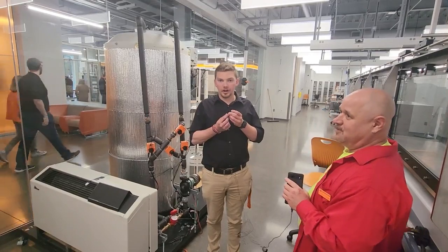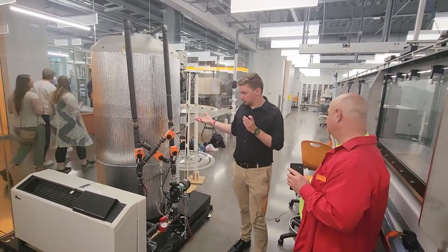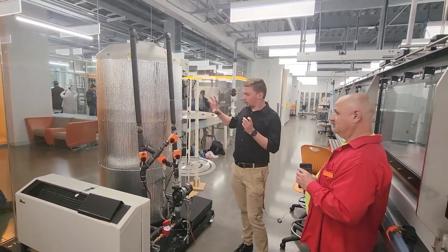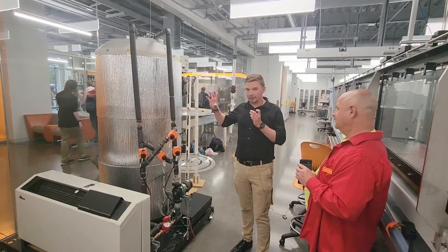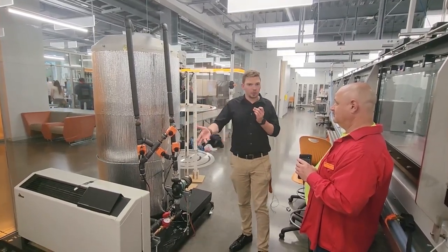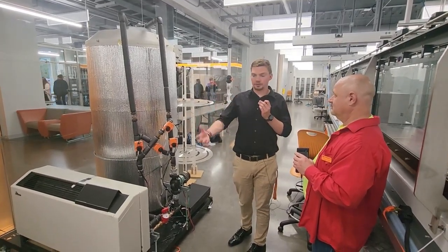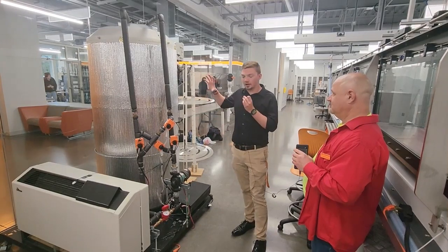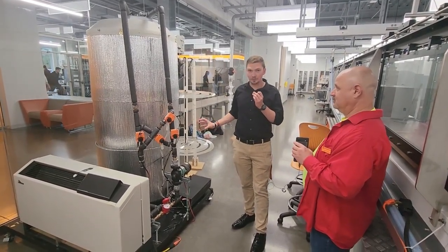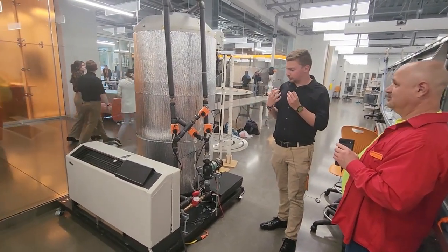Yeah, so I'm Mason. I'm the project lead on thermal solutions, and we're working on a thermal energy storage tank. What this is, is storing thermal energy in water inside the tank and using that thermal energy at a later time to either heat or cool a space. And the way we maximize the energy that we can get out of a system like this is by keeping our hot temperatures at the top of the tank and our cold temperatures at the bottom of the tank separate. The higher that temperature difference, the more energy we have.